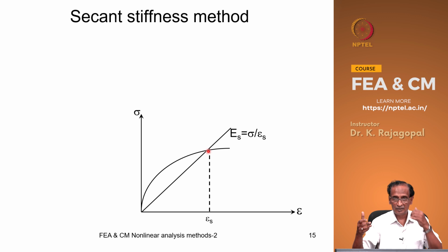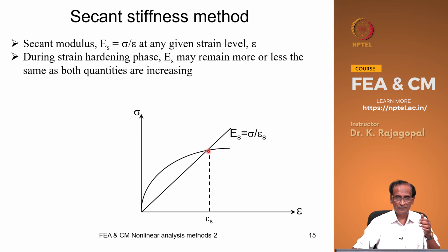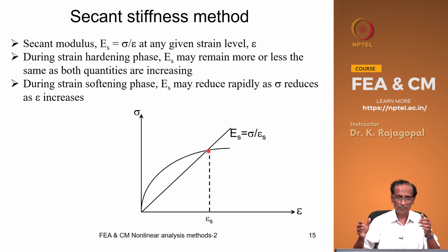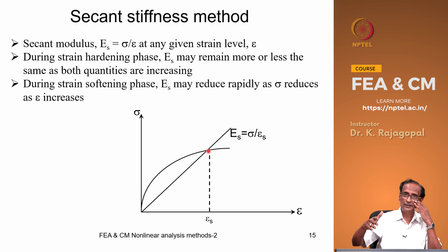As you are reaching the peak your secant modulus will reduce, and especially in the strain softening part your stress is decreasing while your strain is increasing.